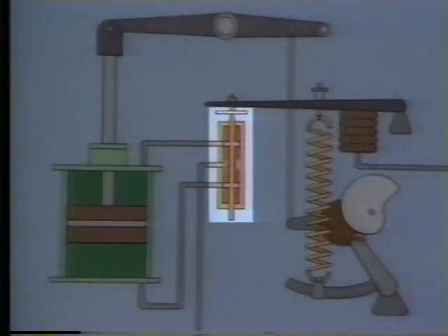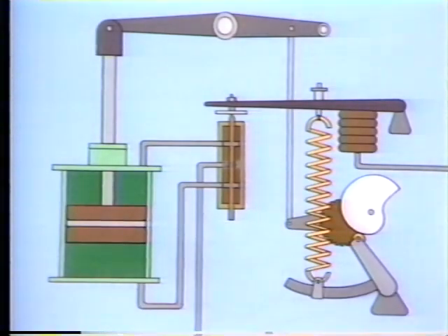This illustration of the pilot valve shows some of its inside parts, so we can see how it works. Here we can see that the pilot valve has 3 air lines connected to it. The middle line is usually connected to supply air from the plant's compressed air system. In this example, the other 2 lines are connected to opposite sides of a piston actuator.